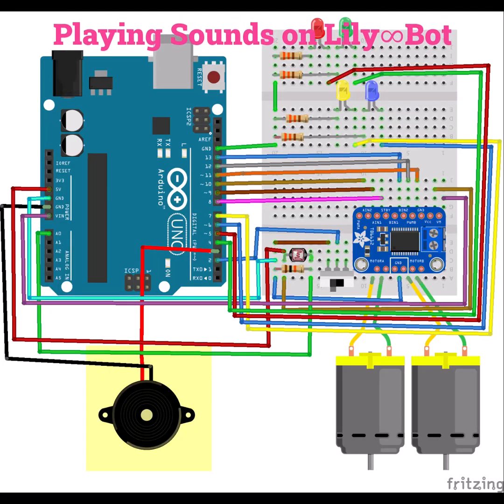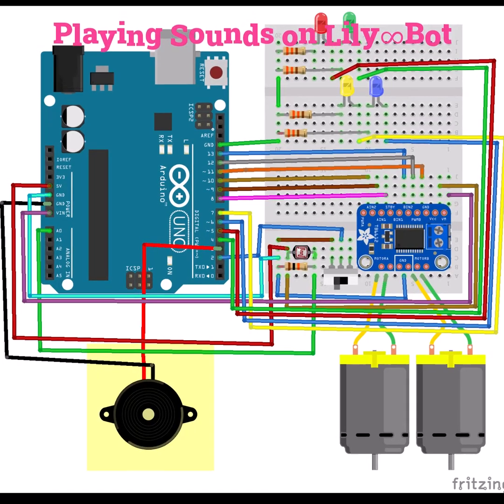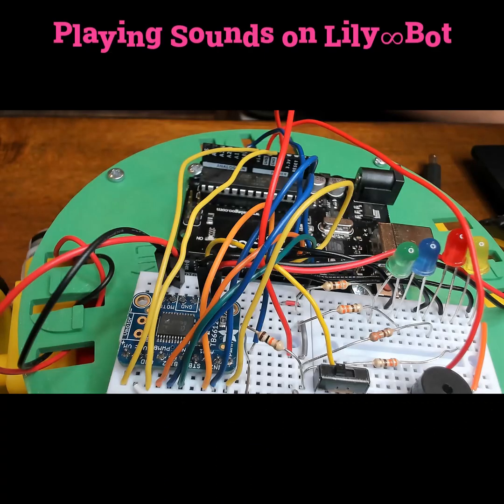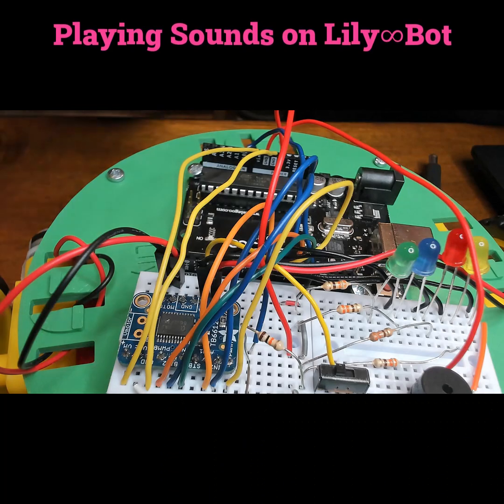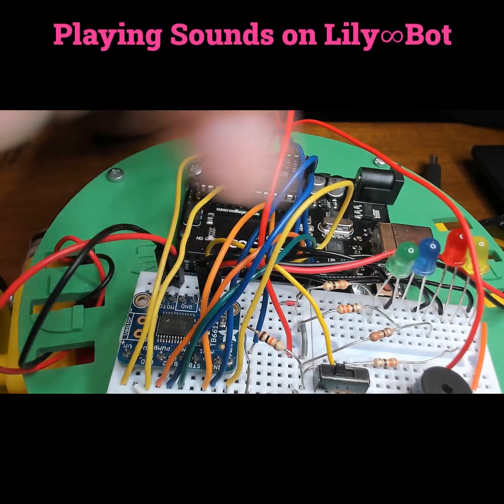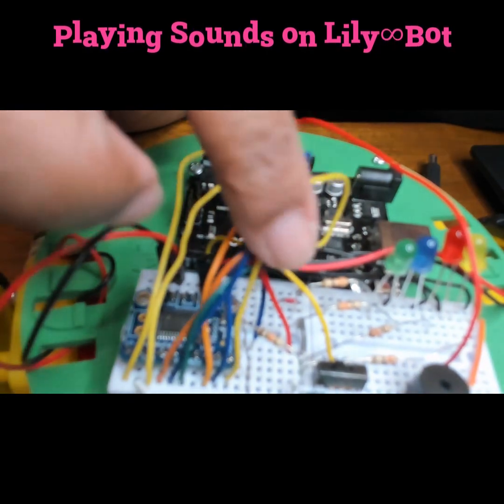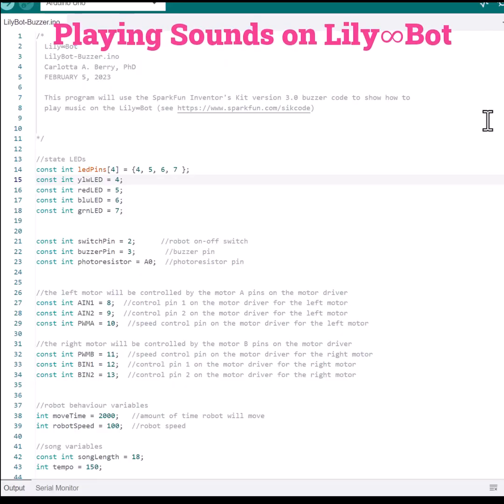So here's the wiring diagram for Lily Bot created in Fritzing. The buzzer is at the bottom center of the screen and the red wire goes to pin 3 and the black wire goes to ground. So here we have Lily Bot all wired up. This is our motor controller, a switch for turning Lily on and off, and the buzzer that will play the sound.